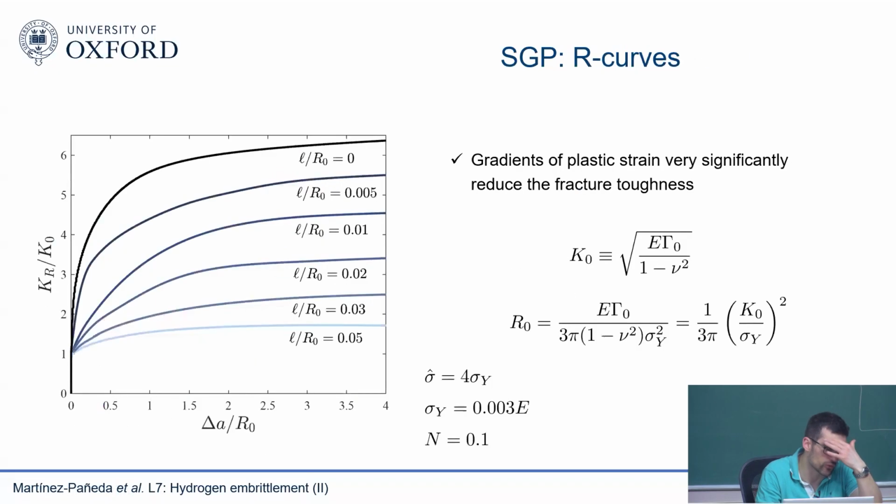So then what we look at is this crack extension, the R curve. So we simulate the propagation of cracks, and you can see, as you expect, cracks initiate when your applied K equals your toughness. Remember the definition. And then your cracks propagate until you get what we call the steady state fracture toughness, where basically your crack just grows unstable. You stop dissipating plasticity. And this is the result that you get for conventional plasticity, so you assume the length scale is equal to 0.